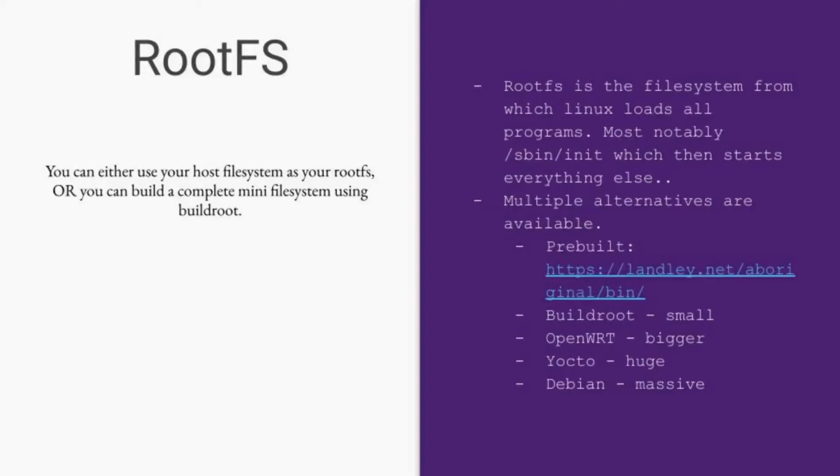So one workflow to develop smaller Linux systems is to build the kernel separately and build the RootFS separately. You put the RootFS on an SD card, and you have your Linux kernel on a separate partition on that SD card. When you recompile the kernel, you just copy the kernel itself. And when you need to install an application, you can just cross-compile that application and move it to the RootFS, or you compile the whole RootFS and just copy the files that have changed, right? So it's a way to incrementally test things when developing. You can build the kernel and the RootFS separately.